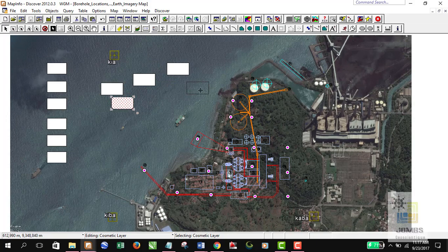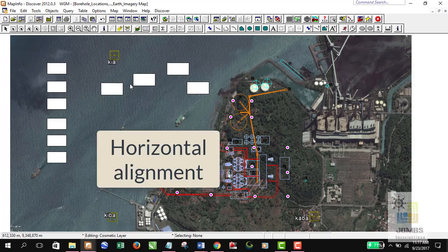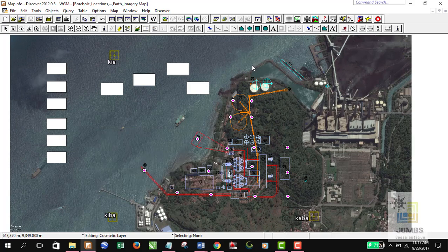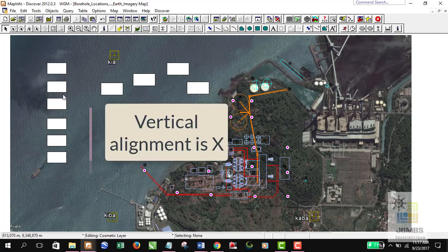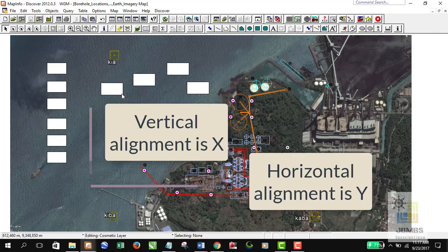Okay, so I have four rectangles here. All right, I would like to line these four rectangles into a straight arrangement. To do so, we need to pick our object reference first in order to set the coordinate reference. Remember, these vertical lines are with respect to the x value, and this horizontal line is with respect to the y value. All right.